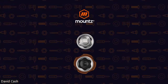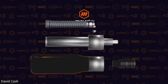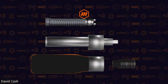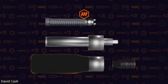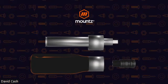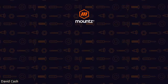As the screwdriver is rotated, those 3 ball bearings ride inside that cam and push on another ball bearing, which compresses the spring. So we have that radial cam design with the different ball bearings to give us a really nice, smooth, and consistent compression of that spring.